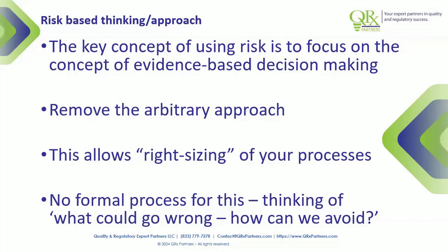I gave the example of management review, but I can talk about preventive maintenance and calibration. Many of the things that are time-based, there has to be a risk associated with it. Calibration doesn't tell you the next measurement is good. You calibrate at a future point to know all of the measurements in between were good. Well, how much product did you build in that time that was measured? That's the amount of risk associated with it, because all of that could be bad, right? If your future calibration shows that it wasn't working.